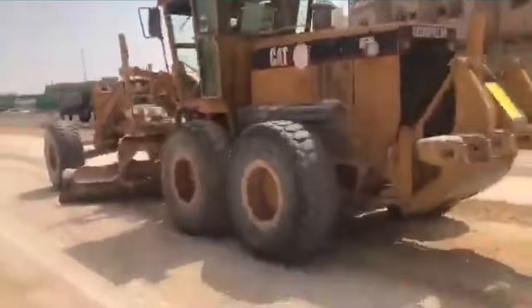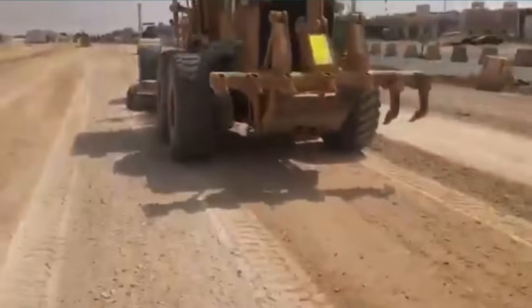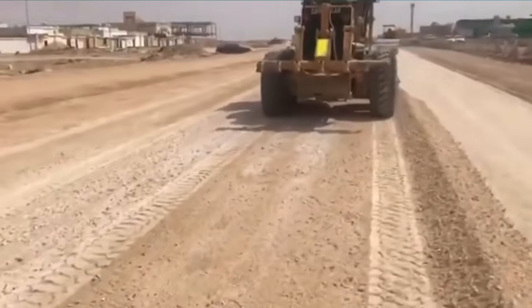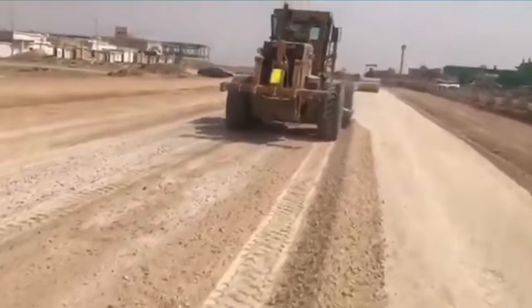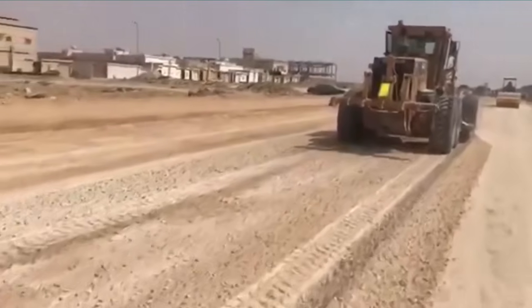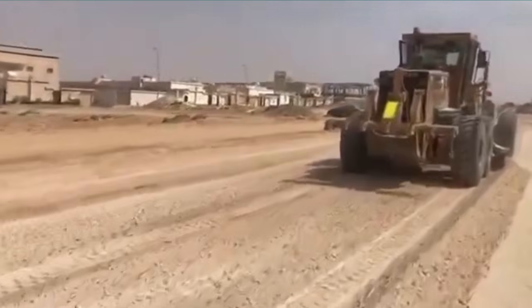The higher properties of subgrade soil shall be blended with granular aggregates to ensure more durability. Normally, a mixture of 1:2 by volume, that is, 1 part granular aggregates and 2 parts good subgrade soil, is blended thoroughly to produce a good subbase material.